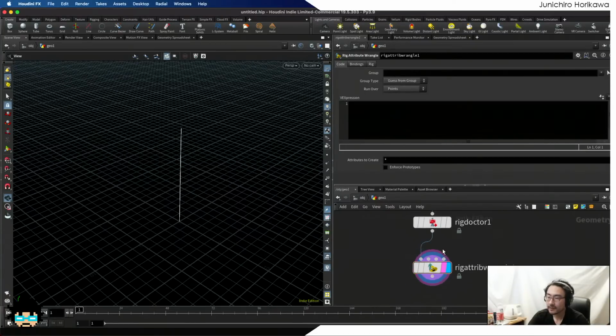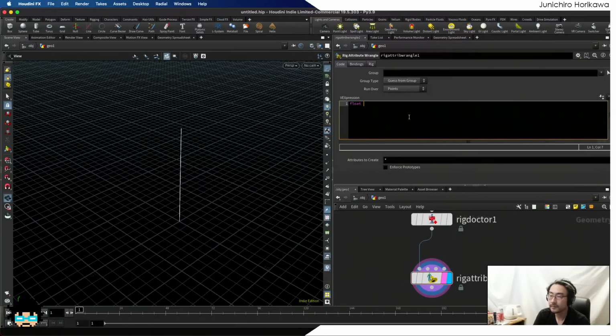Let's try this out. First of all, let's create a parameter value based on the point number and the total number of points. The point number is pt_num, and let's divide that by the total number of points, so that you get a value between 0 and 1 as a parameter to define the position on the curve.